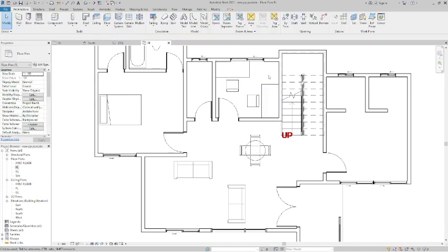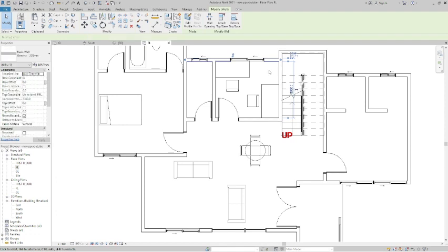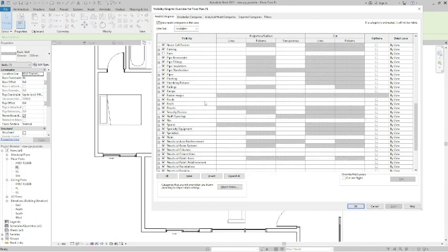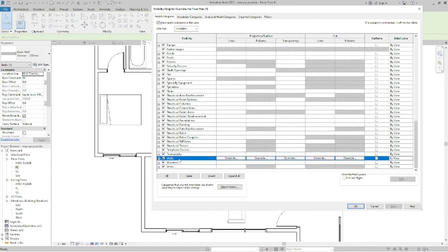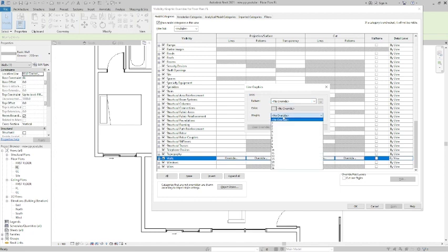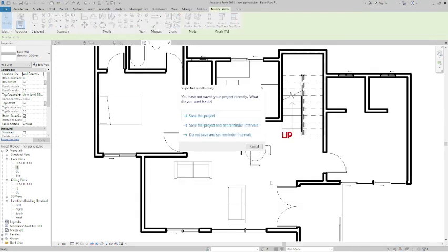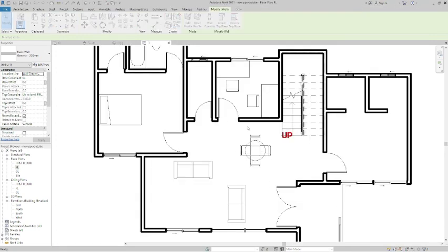So I'll select the walls for this wall. I'm going to increase the thickness of this wall, the line width. So VG on the keyboard. Go to walls, click on it, and cut where we have the lines. I'll click on the override and change the width towards 6 line. Okay, so I'll save my project.